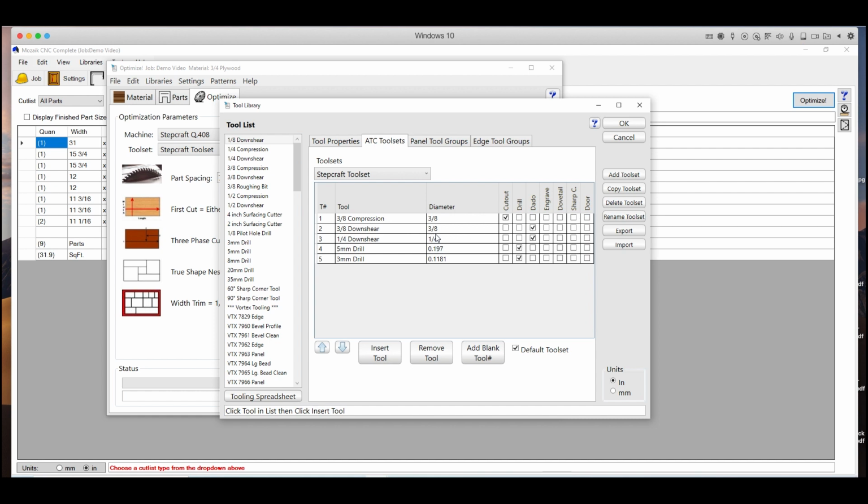Now the reason I have two is sometimes I have dado pockets that are to fit 3/4 inch panels so they interlock. So those would be 0.74 inches wide.